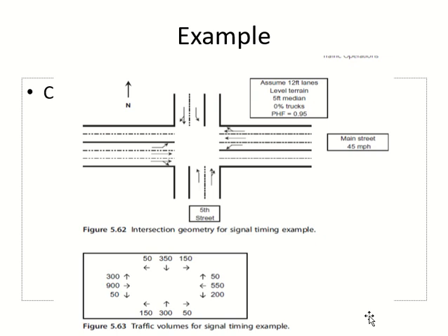Then we have to decide how we will divide this volume. What percentage of it will be from this lane and from this lane? Similarly, if I had 2 lanes for left turning, then I would have to decide how much from each lane. Whenever you have more than 1 lane for the same movement, you have to decide the percentage, and you cannot say it's equal.